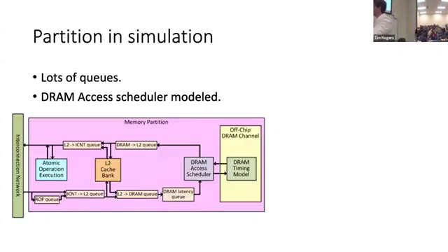Okay, so we model this inside the simulation infrastructure that you use. We model it like this, and we basically have a whole bunch of queues here, and every computing system does look like this. There are queues everywhere in a modern computing system because not all the rates match up, so you've got to have FIFOs everywhere in a system. The general way that this works is, if something is coming in from the interconnect, let's say it's a load or a store.